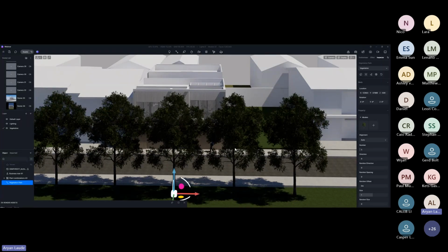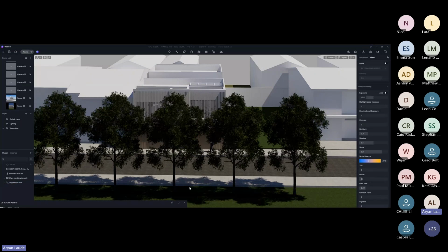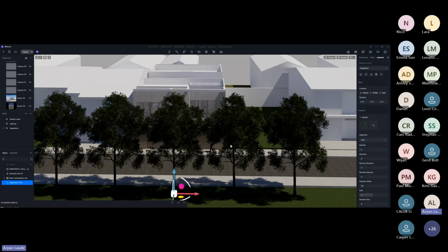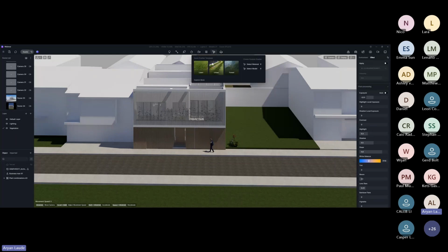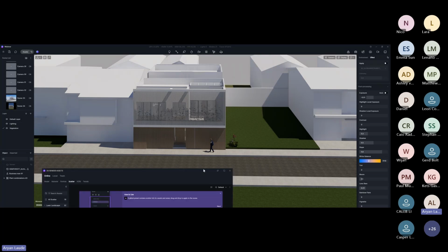With D5's exclusive feature, the scatter tool, it will help you build your scene within a few seconds. All we need to do is go to the asset placement area and select add scatter. We can choose from our templates. Since we wanted to add a lot of trees, I'll select the forest options.